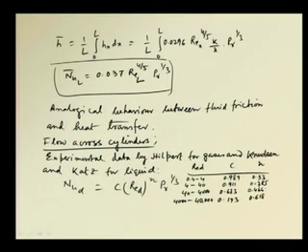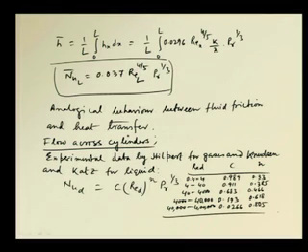We see that the index is gradually increasing and the constant term is gradually decreasing. Then for 40,000 to 4 lakhs, in this Reynolds number region, C is 0.0266 and n is 0.805. So these are the different values of the coefficients and the different values of the power of the Reynolds number, based on the Reynolds numbers.